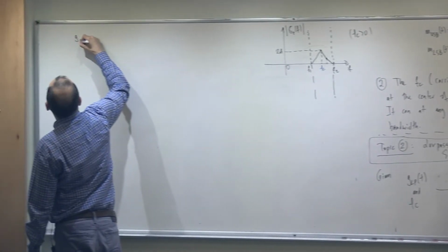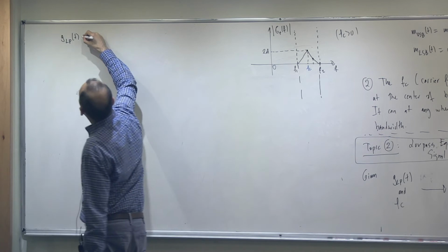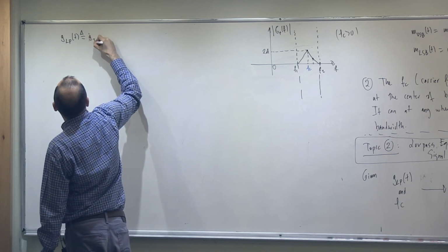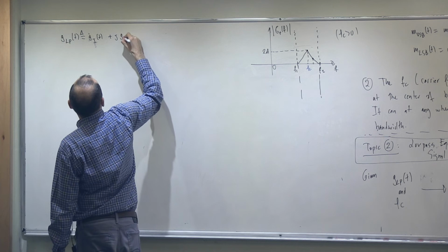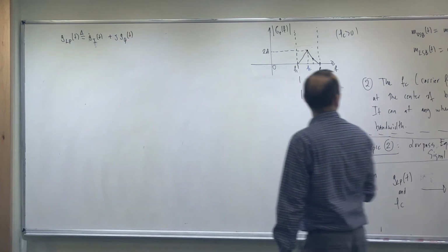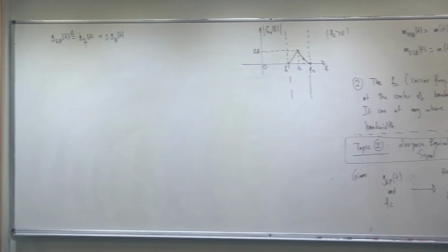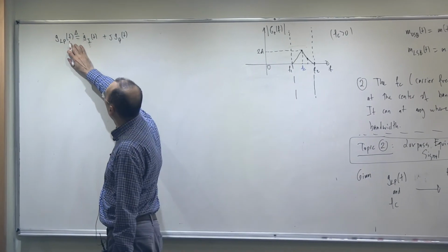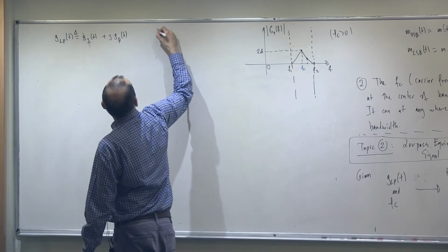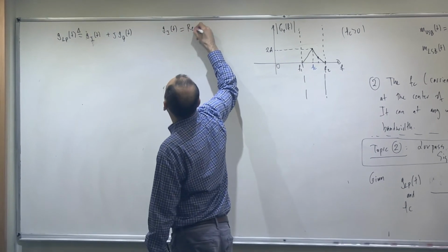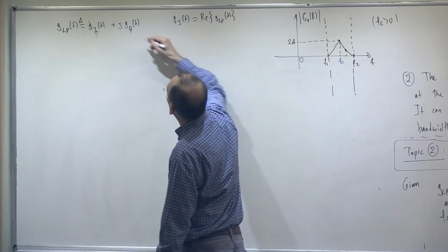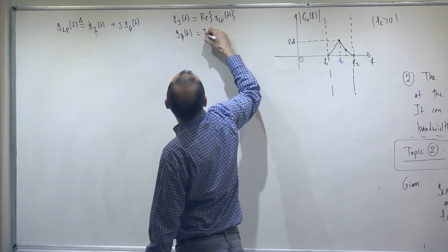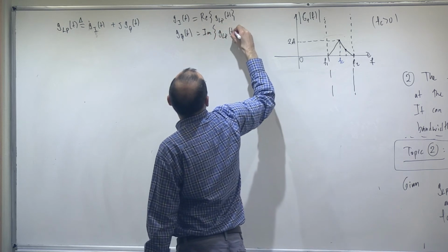Now, we have said that the low pass equivalent signal is complex valued. So let me define the following: Gi of t plus j Gq of t. Because we have said in note number 1, I have just erased this one before, this is a complex valued signal, the low pass equivalent. And this is its real part. So Gi of t is obviously the real part of this, and Gq of t is the imaginary part of this. Okay.